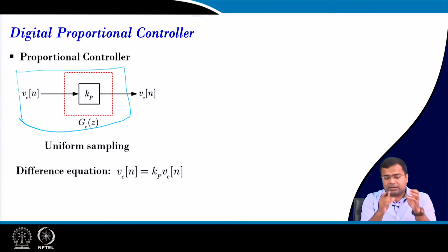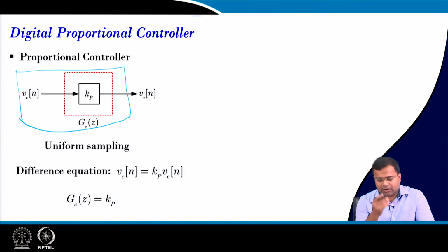The computation time of the proportional controller, the integral controller and the derivative controller may be different. But if we synchronize them with respect to clock, then all of them will be updated at one time. So, we will do a clock synchronized PID controller. So, here also you can use a clock to synchronize, and it is just a simple multiplication.